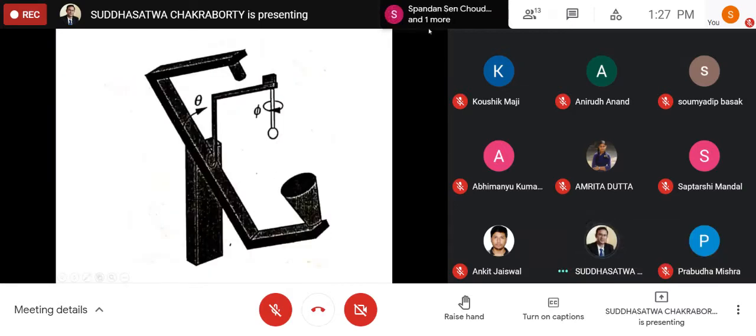Forget about the mirror. In the type B meter, what we have seen is that my source is rotating left and right, that means in a horizontal plane as well as in the vertical plane. My sensor is fixed. But for type C goniometers, my source is rotating at the horizontal angle and my sensor is rotating at the vertical angle. So that's how we are going to get the sphere, isn't it? We are supposed to get a sphere.